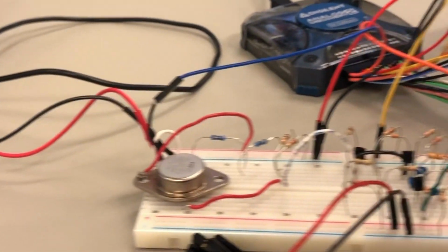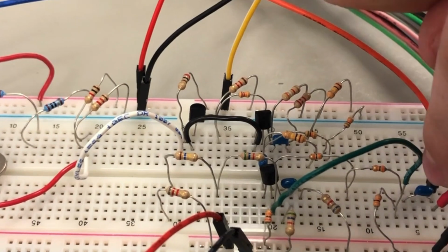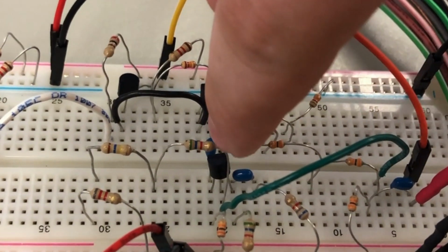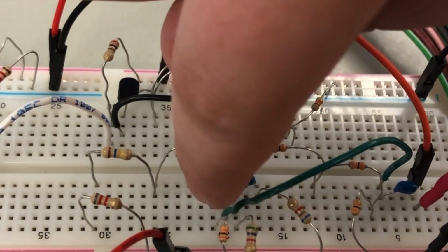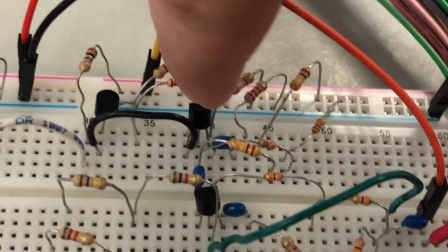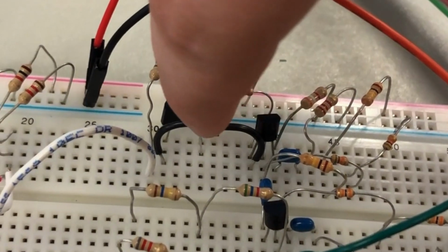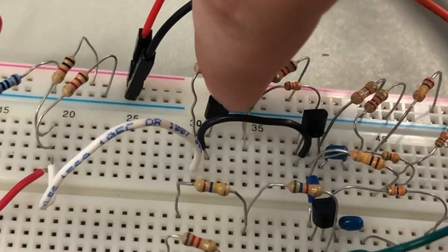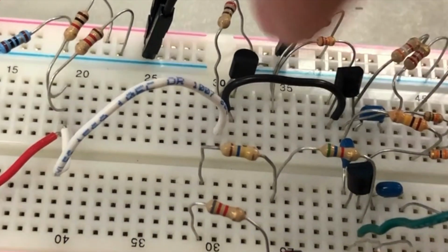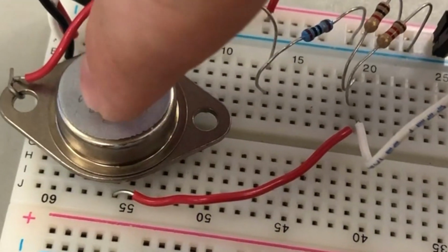So, as we can see, we have the input going into here that then goes through that capacitor, goes through this wire, that goes through this transistor, and from the emitter of this transistor is the output of the first stage. The output then goes through this transistor, through this capacitor, that goes through this transistor, and goes through this wire to this transistor, which acts as a buffer to this common emitter amplifier. And that's the second stage. That then goes through this wire to the base of this transistor.